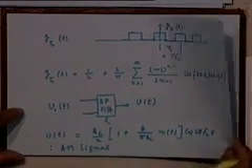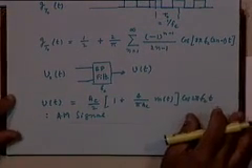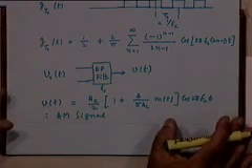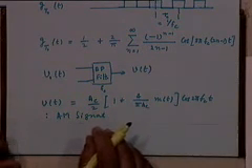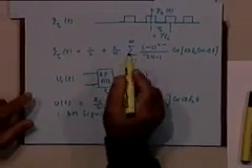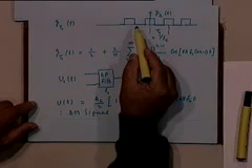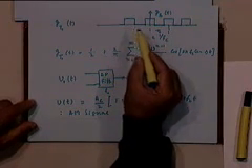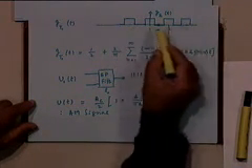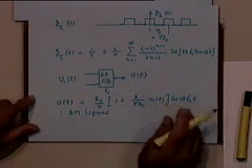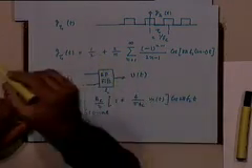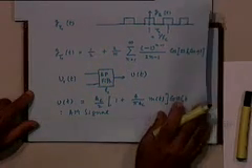Now suppose we wanted a pure DSBSC signal without the carrier component. We can still apply the switching idea. The only difference we need to somehow create is that instead of multiplication of alternate half cycles with 1 and 0, we need to multiply the input waveform with plus minus 1 to make this waveform zero mean. The DC component of this waveform should become 0, so that this factor half does not appear, which multiplies with the carrier component in the other term, right.